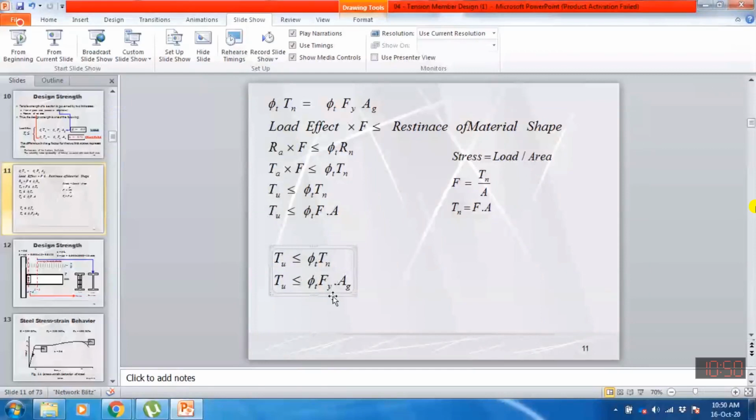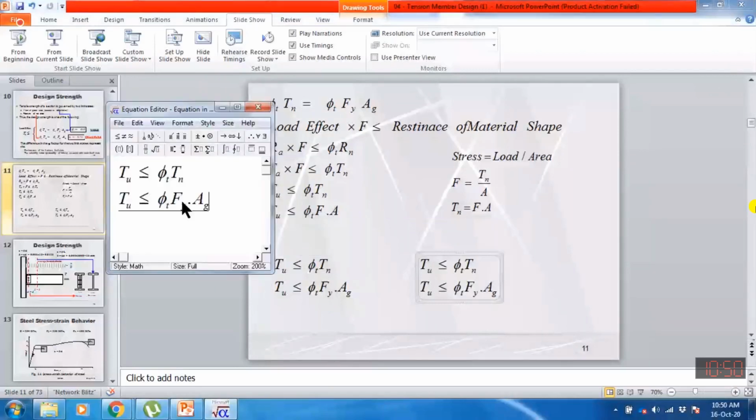In this equation, I'm considering the rupture failure. Rupture failure will always occur due to ultimate stress, when applied stress will be more than or equal to ultimate stress. And this stress will always occur at a net area. So this is my second capacity. Later on, I will change the net area with another area, but I will explain when I'm discussing that topic.